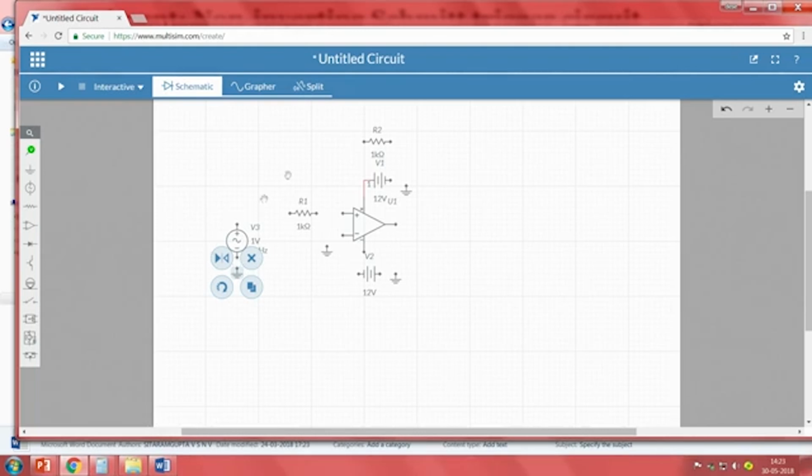So, how to do the connection? Simply wherever you want to create a wire, go to the end tip and press left mouse click, and automatically the tool will be converted to the wiring tool. Then move your mouse. Wherever there is a connector, it automatically shows the zoom out function.